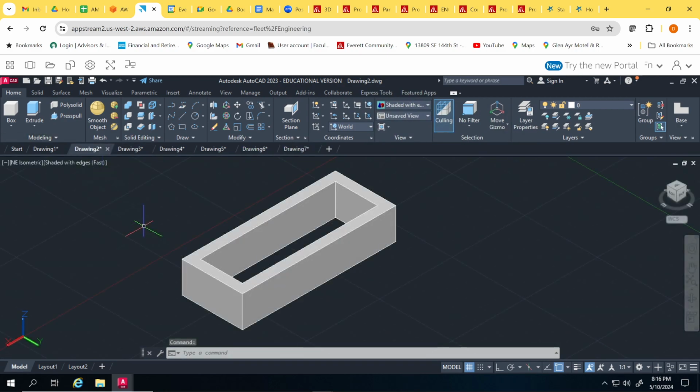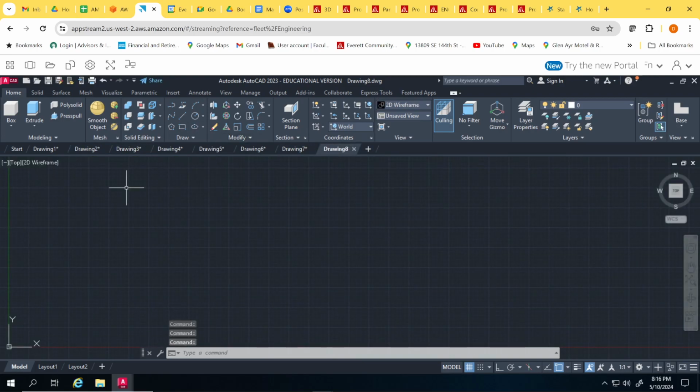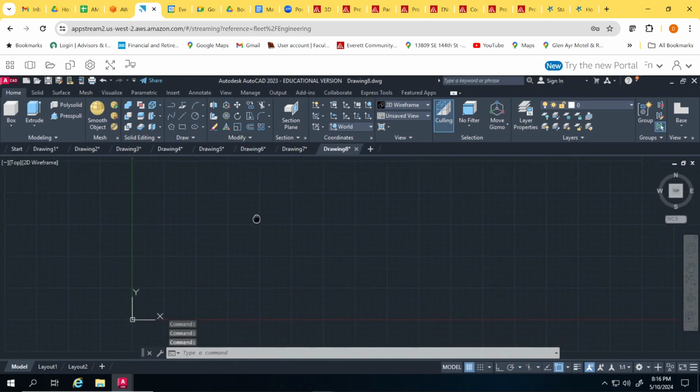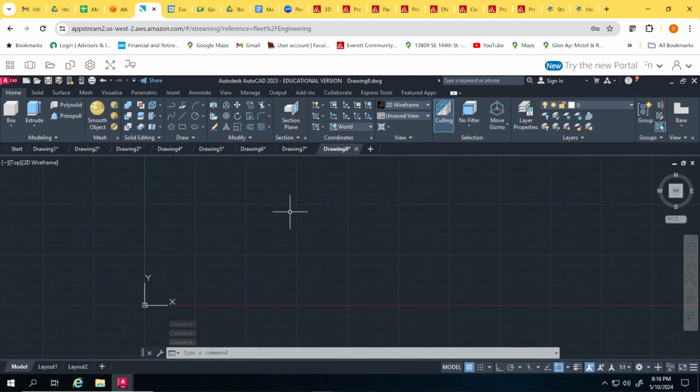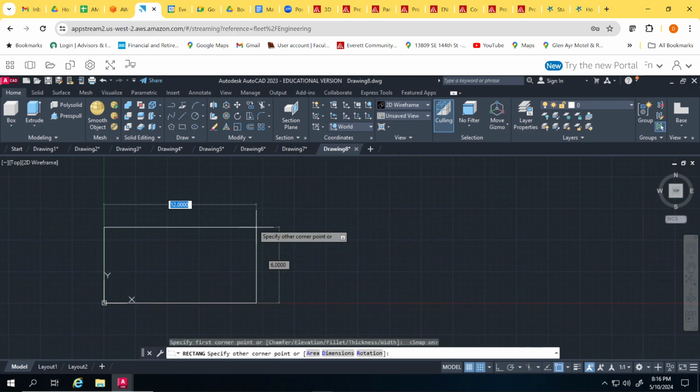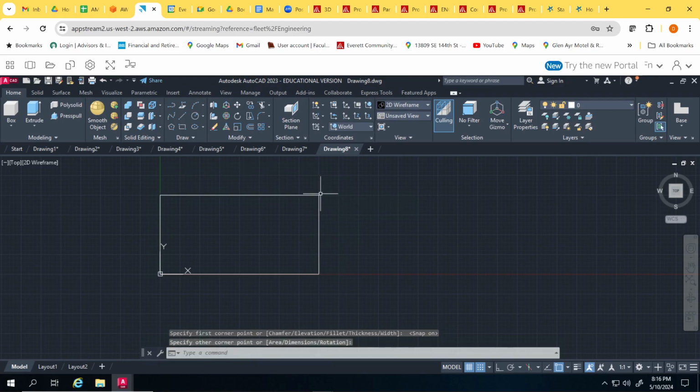Let's try drawing number 2, where we have 2 simple rectangles. We'll do the same thing. Create a new part. I'll just slide the axis. I'm not worried about my grids. I'm just trying to show you how to use the 3D feature. We'll use rectangle next. I'll start here at 0, 0. Notice it's not giving me a 0, 0 because I have to turn the snap grid on. I'll snap to this point and drag it out to some random position.